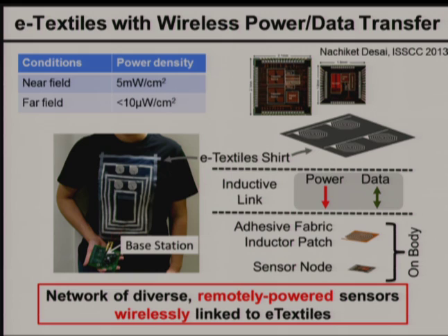But here I've just showcased a device where you have a medical patch on your body, and that patch is powered by a transmitter coil on your T-shirt or so. The patch is powered, and then it can also wirelessly transmit data back on the same channel to the transmit side, which can then be connected to your cell phone or so. So this is also possible. But if you want to truly decouple from the transmitter and increase the distance, it is also possible to power in the far field, but then the power drops off significantly, and it becomes kind of impractical after a certain distance.